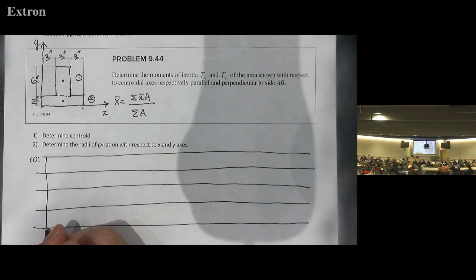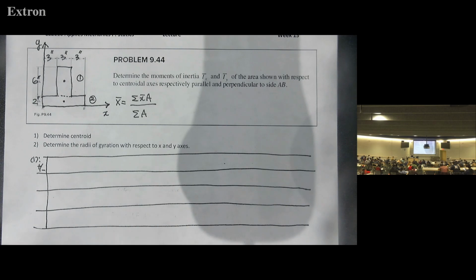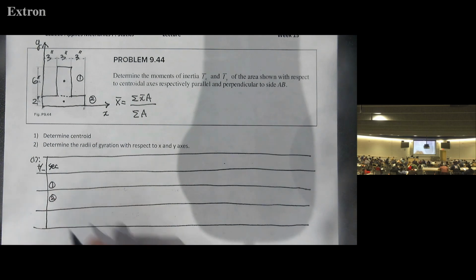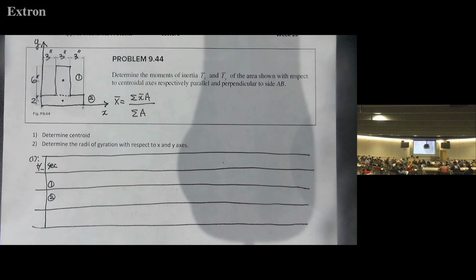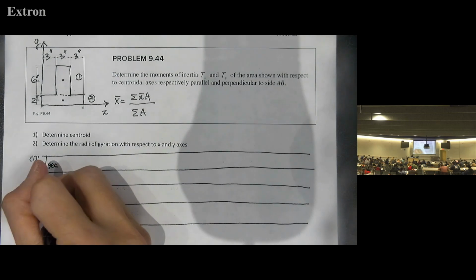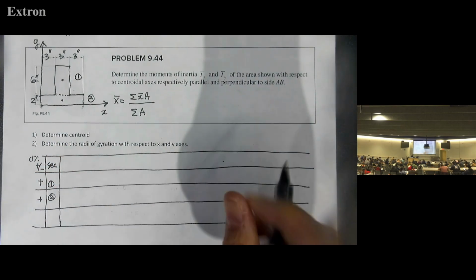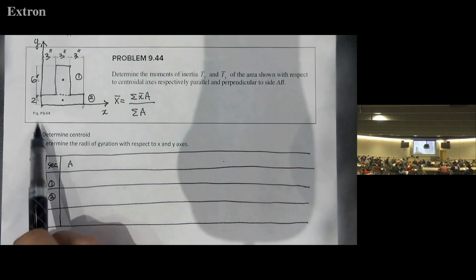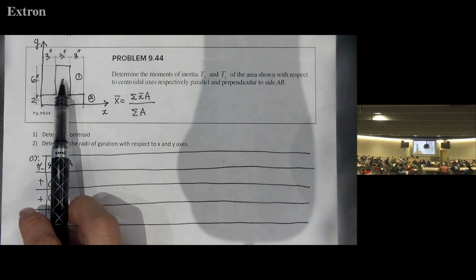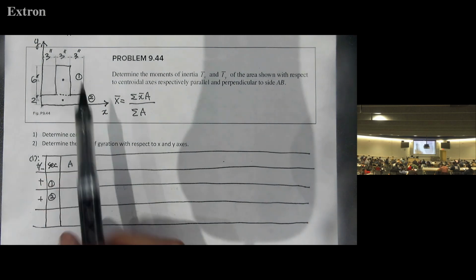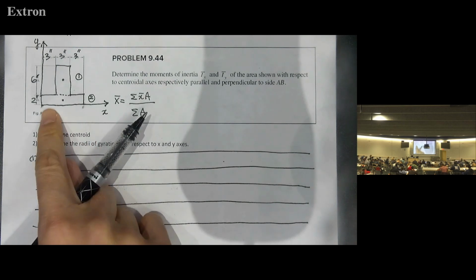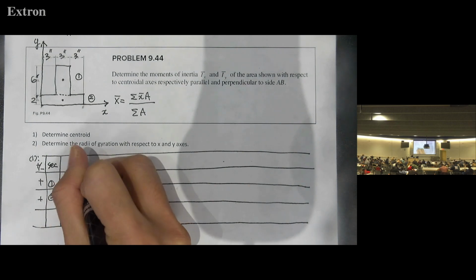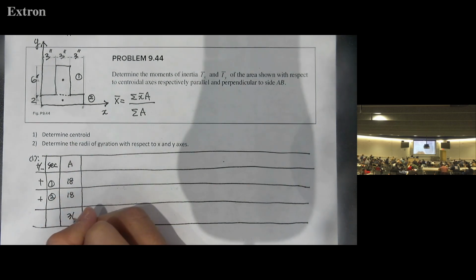Okay, and then the first column is plus/minus, right? And then the second one, section. We have 2 sections, 1 and 2, and both are summed together, so all plus. And now the easiest one first, area of each shape. This is the area of the first rectangle, 6 times 3, 18. Area of the second shape, 2 times 9, 18. Right, so the total area is 36.